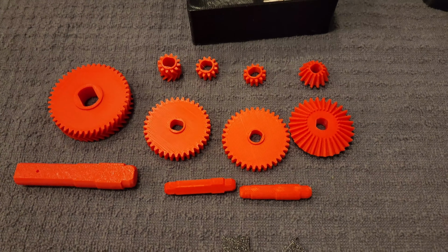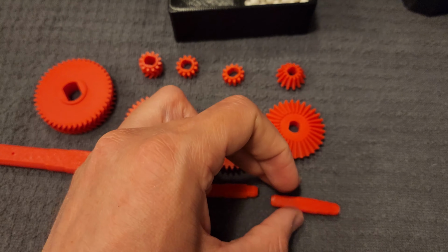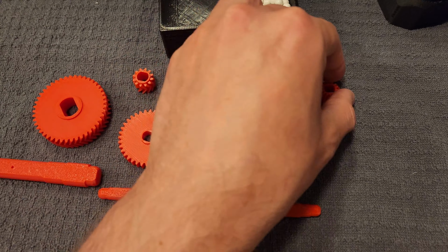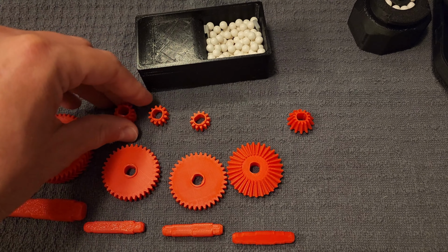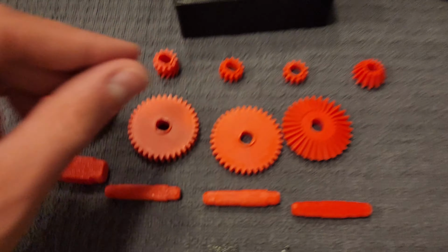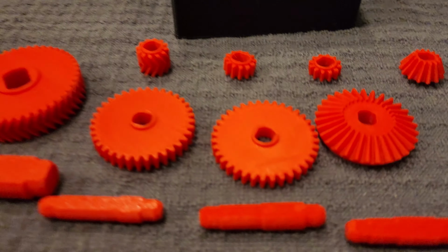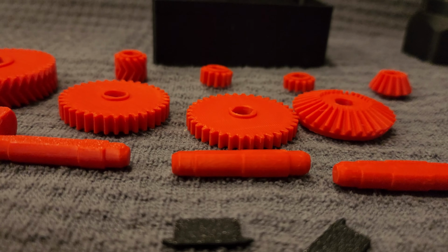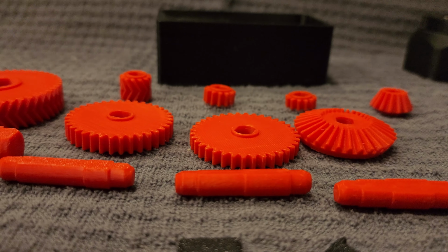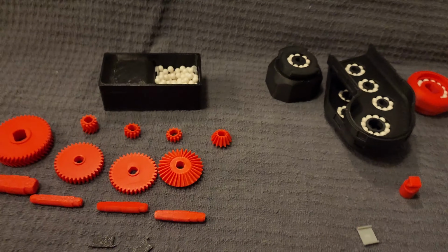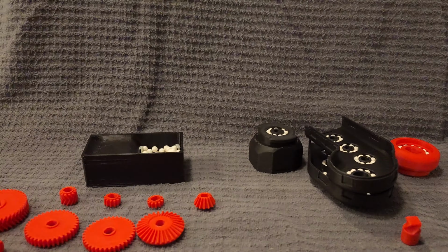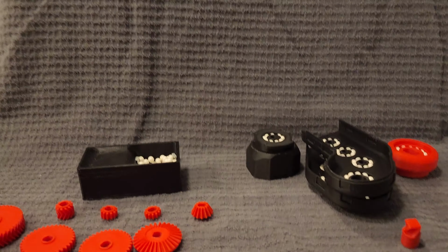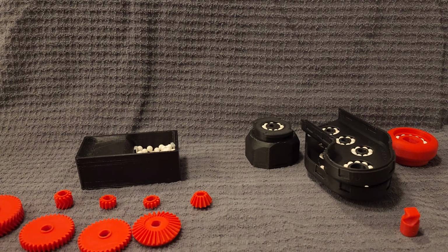Only one of the shafts has just one gear. It's going to be the input shaft with the biggest gear, and the three other shafts will need two gears each. And you got to pay attention to the thickness of the face width of the gears. So the thicker ones are going to be on the first shafts, and the further you go through the gearbox, the thinner the gears become. So let's assemble the first shaft.